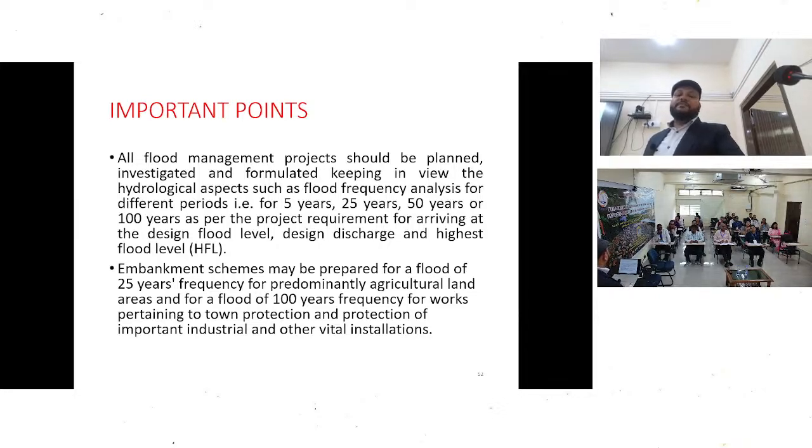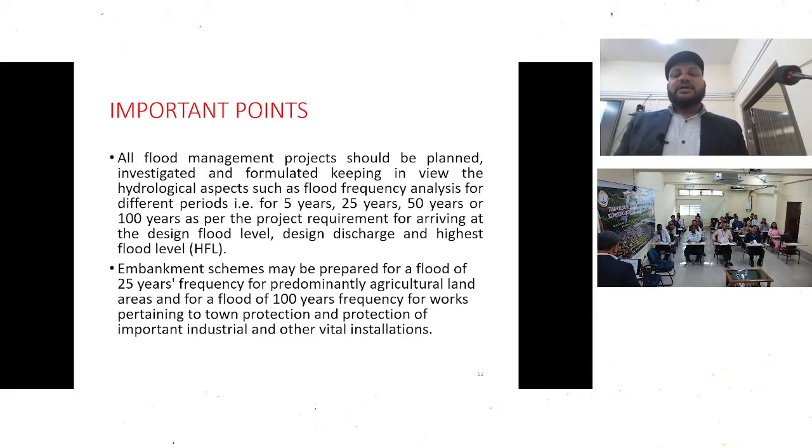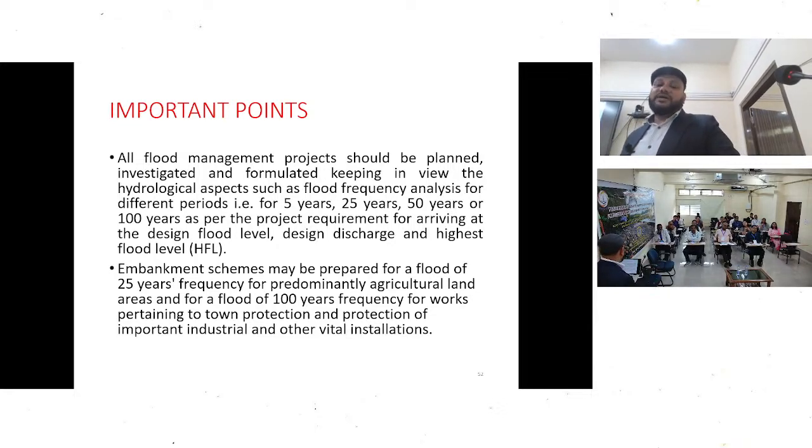All flood management projects should be planned, investigated, and formulated keeping in view hydrological aspects such as flood frequency analysis. This is very important because we construct and design the project. Cost depends mainly on flood frequency. How many years do we want this structure to work, whether 5 years, 25 years, 50 years, or 100 years.